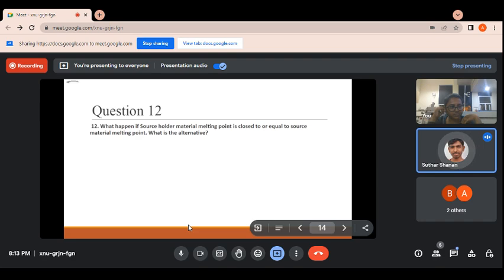Okay. So basically, you are saying that only for SU8 we go for the soft bake first. Soft bake, actually, the temperature is different. You can see, for positive and negative photoresist, the soft bake temperature is 90 degrees for 1 minute on a hot plate. Okay. And for SU8, what is the temperature? For soft bake, the temperature is 65 degrees. Then we go for 90 degrees. So here 90 degrees is called the hard bake process. But for positive and negative photoresist, the hard bake temperature is 120 degrees, right?